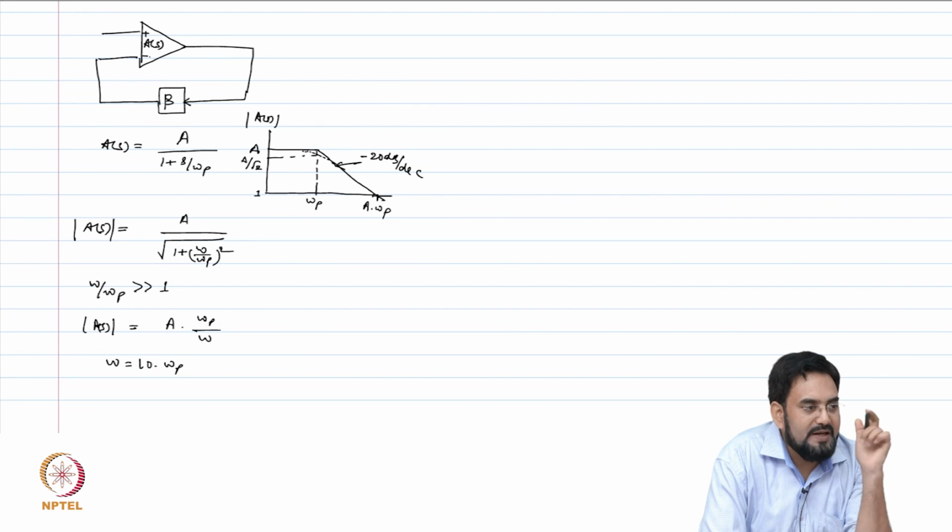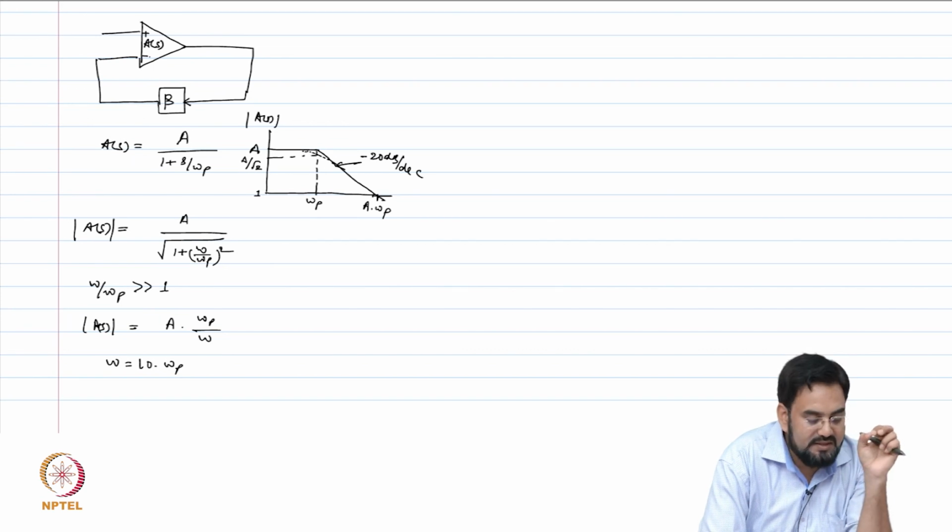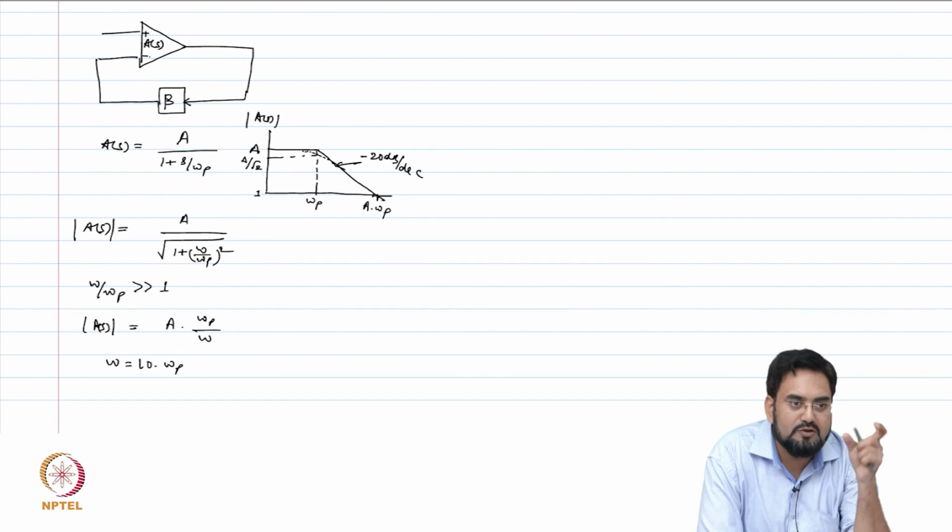Overall loop. By looking at the loop gain, the pole of the loop gain, can you just say that it's stable or unstable? You should look at the gain margin. Phase margin. No, not phase margin. I am looking at the pole location, left hand or right hand. So when you say left hand, right hand, that is defined for your closed loop, not the open loop. And when you define the phase margin, gain margin, that is for the open loop system, your loop gain.